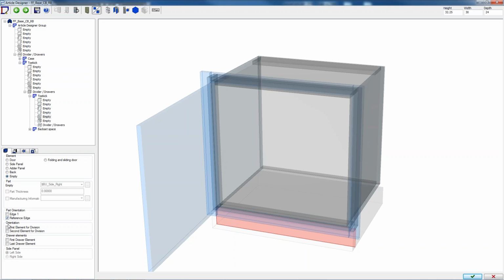Quick question. This toe kick will be sitting on the bottom of the box, right? So the dimension overall will be different than 4 inches. It'll be 5 3/8, I believe. So 4 inches will be visible from under the frame.